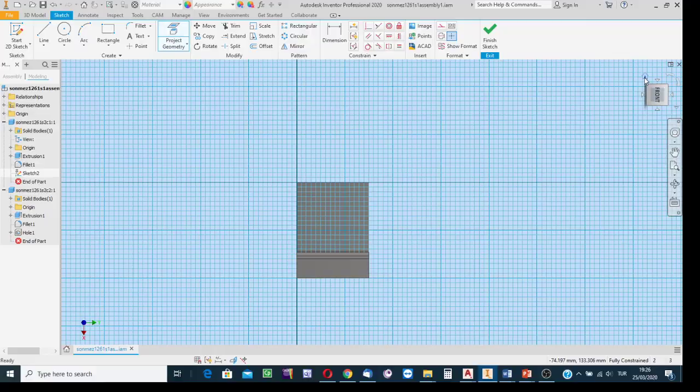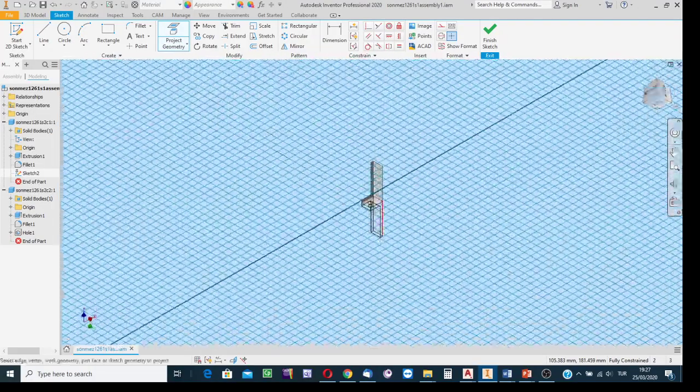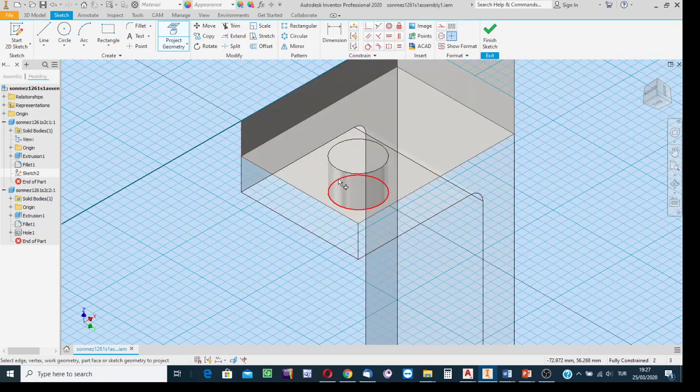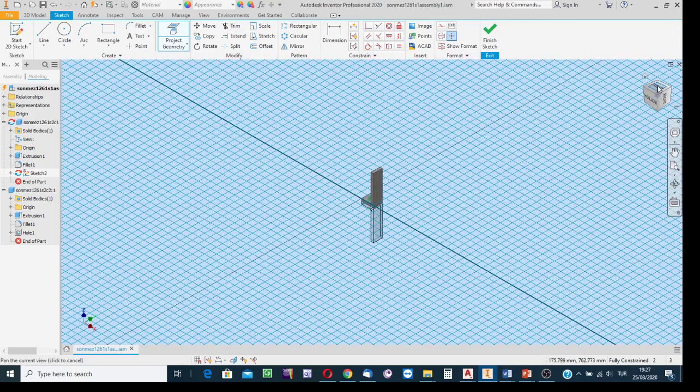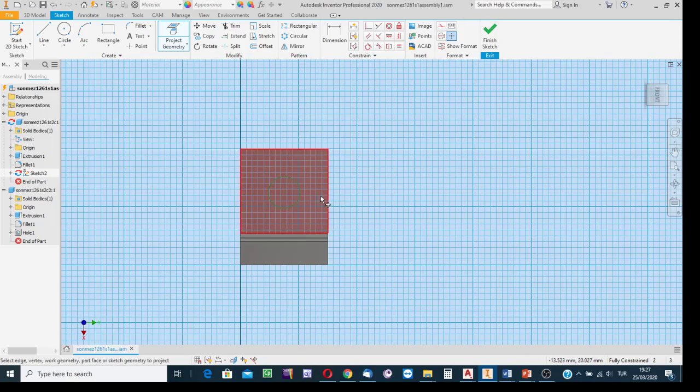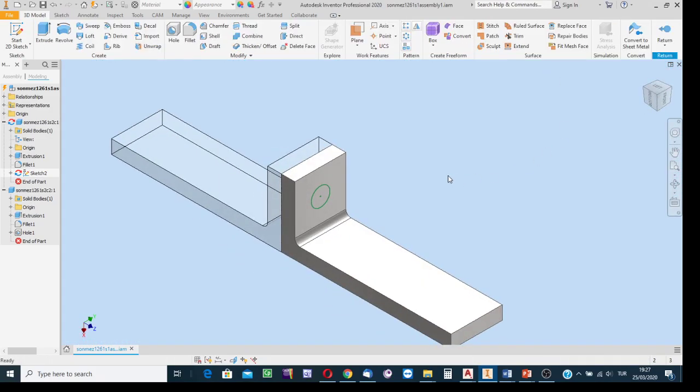Okay, and then, if you want, you may clearly see and indicate the edge of the available hole, this edge or the other edge, no matter. Indicating the edge of the existing hole, you see I managed to obtain its projection over the selected sketch surface. Finish the sketching stage, and now over the surface I have the projection of the edge of the hole, the already created hole. It is within the first component, and now this area is the profile.